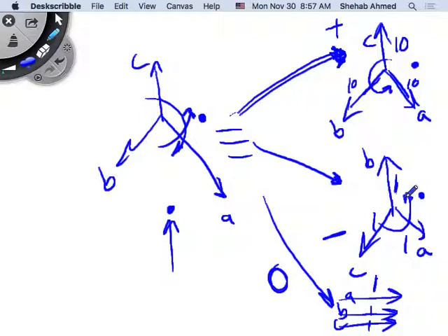If you apply voltage, you will have current, right? So you will have current in the winding, but what is it doing? You're actually decreasing the torque. This is opposing the torque produced by the positive sequence, right? So you're heating up the motor, and you're not going to get the same amount of torque. You brought the torque down, and what happened to the current? It went up, because you added some negative sequence current to your machine, right?